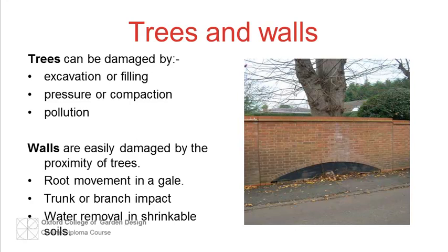Details are shown in the current edition of BS 5837. For instance, using a geogrid fabric, a Type 2 subbase, and a porous block pavers or no fines gravel topping. The area affected should be restricted to 20% of the root zone.